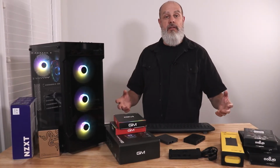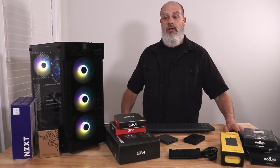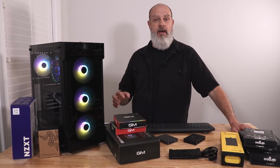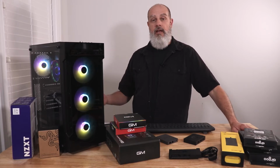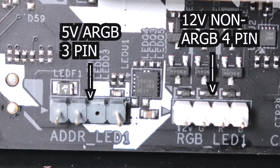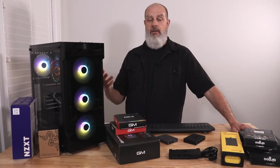So let's go ahead and talk about the two main types of connections that you're going to find out there. The first being a 5 volt connection, the second being a 12 volt connection. I'll talk about the pinouts to each of these in just a second and how they're wired up. But this will be one of the more important things to take away from this video. And what these two connectors really mean, at least this is how I associate them, is the 5 volt connection is the addressable RGB connection, or ARGB, or digital, as you'll see it referred to by any of those names.